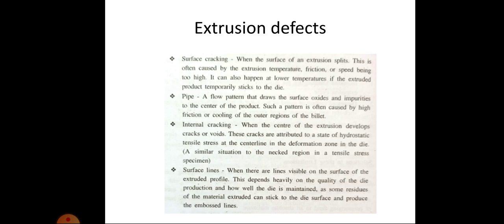First one is surface cracking. When the surface of the extrusion splits, this is often caused by the extrusion temperature, friction or speed being too high. It can also happen at low temperatures if the extruded product temporarily sticks to the die.